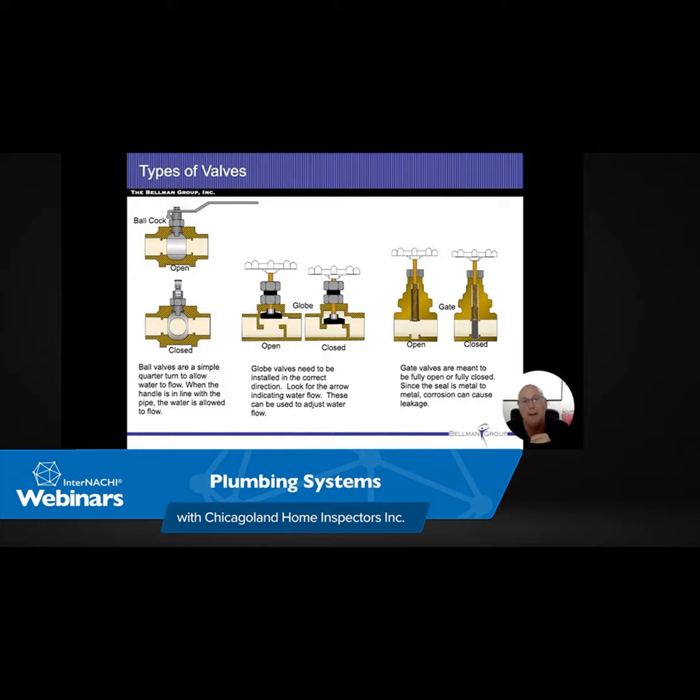When the cold water enters and the hot water is pushed out of the top, it's going to try and recover as quick as possible. So if we only have cold water on the bottom and warm on top, the bottom one's going to go. Once I run out of hot water in the entire water heater, then it's going to recover the top half first. So then only the top element's going to be ignited.